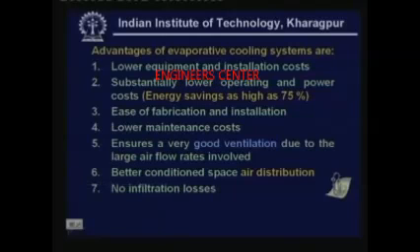And there are no infiltration losses because the air flow rate is very high. Normally you find that whenever you are conditioning a building using an evaporative cooling system, the pressure inside the building will be positive. That means the pressure inside will be higher than the outside pressure. So as a result, if there is any leakage, it will be a leakage of air from the inside to the outside, not the other way. That means there won't be any infiltration of outdoor air into the conditioned space. So there are no infiltration losses, right?